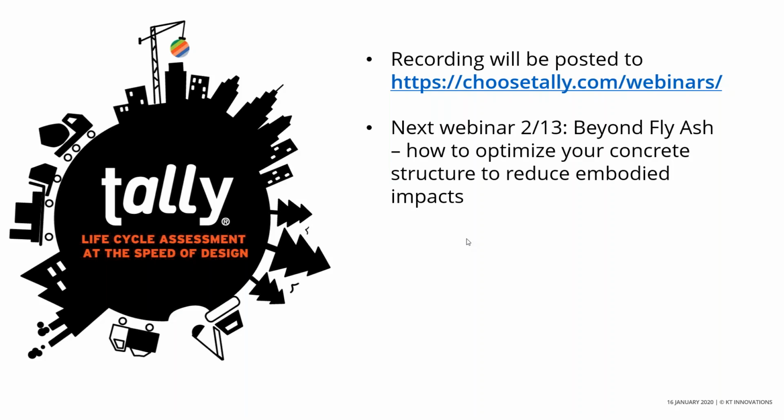We have one here that's actually about how often EC3 data is updated. And actually, that's something that we don't know. It really is dependent upon the manufacturer's EPD. Every EPD has an expiration date associated with it. So when it comes to the EC3 data, it's a continually growing database, and the longevity of a particular data point within there is going to be dependent upon that EPD. If there's data that you want to see in the EC3 database, it really behooves you to contact the manufacturer and ask them to get it in. It's quite an easy process. EC3 has made it very streamlined. That information will be in there. So essentially, I guess it's updated as frequently as new data becomes available.